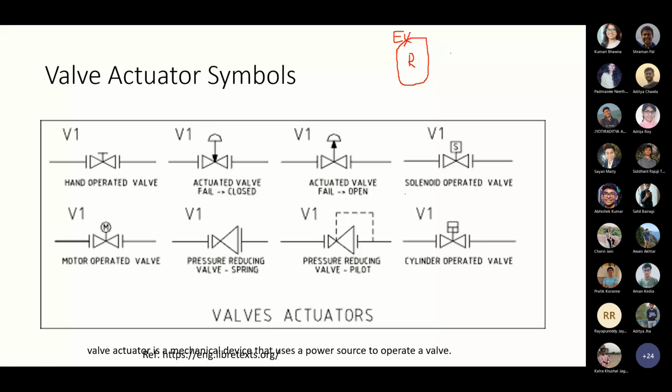When an exothermic reaction takes place, what will happen to the temperature inside the reactor? It increases. So we need to regulate the temperature, because if it rises to a very high temperature, the reaction efficiency will reduce. Another thing is that the process vessel may get damaged or an accident may happen.